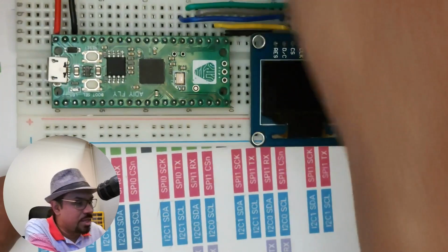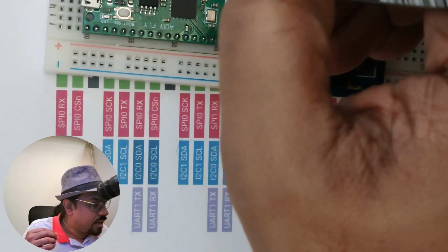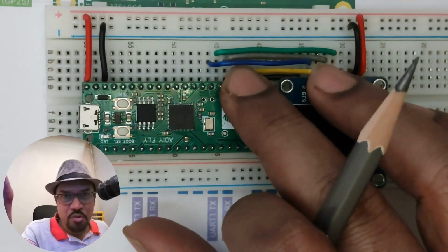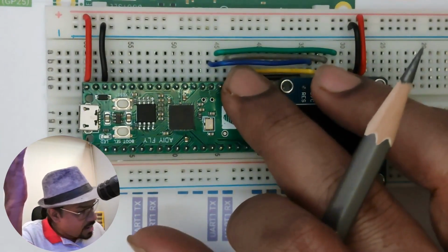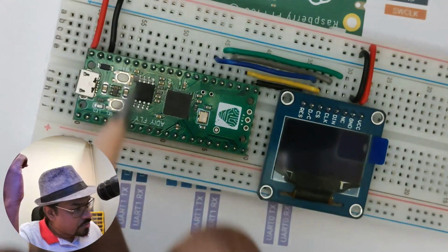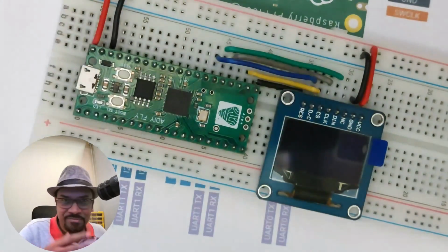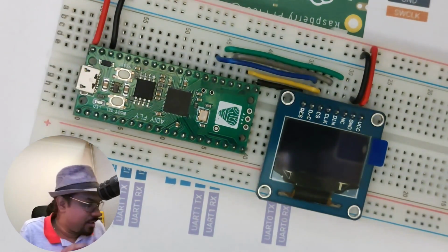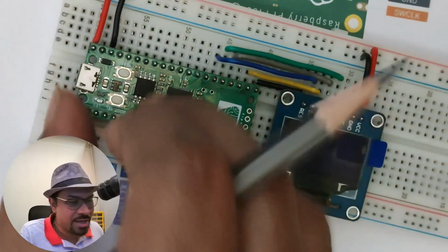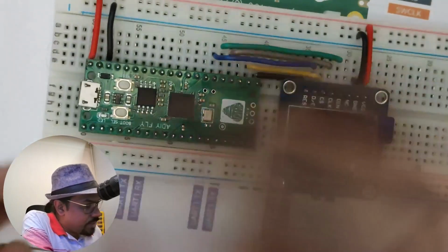You might ask me why they have so many repeated pin connections. Basically for convenience. It's possible that some of you might want to use the pins on top as general purpose GPIO pins to connect to other devices or other sensors, and you want to use this side for your SPI connection. Or you can do otherwise. You can use this as general purpose IO pins for other sensors, and you can also use this as SPI. So you can mix and choose the way you find convenient, right? That's why there are repetitions of these SPI connection possibilities and also I2C connection possibilities on a typical Raspberry Pi Pico. So I have made this connection in here.